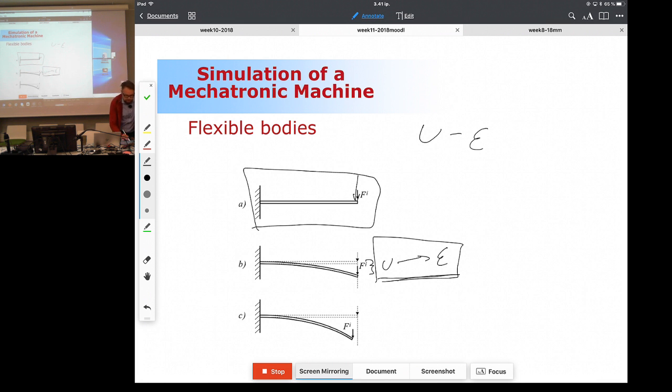If I assume this strain displacement relationship to be linear, such that this is a simple relation, then when I'm loading this structure, this free end always remains on this loading line, which is all right if the deformation is small. But if the deformation becomes large, then soon the deformation will be something like shown here. This free end will stay in this loading line, and you can see this is not how the beam acts in reality.